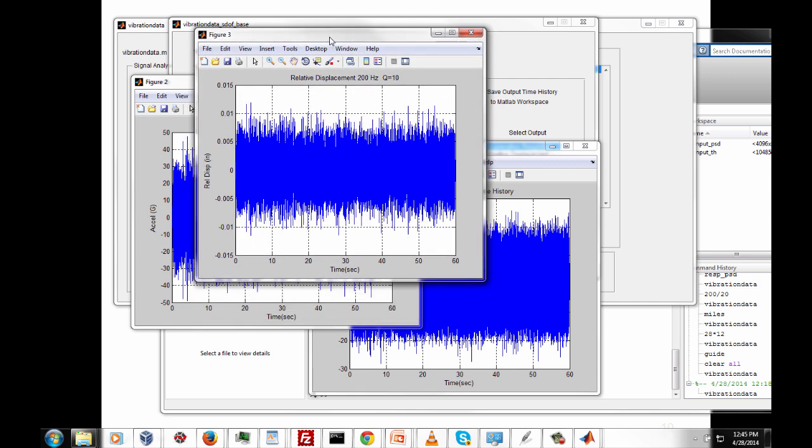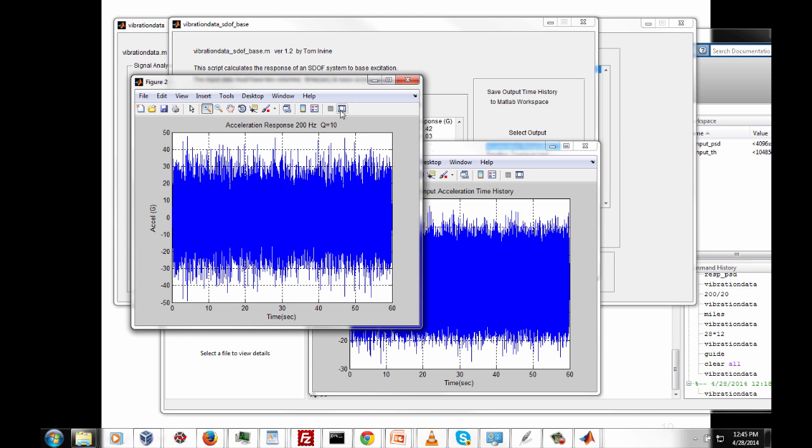We've got a relative displacement response time history, and eventually we're going to be looking at these, especially when we get to circuit board analysis, dynamic analysis of circuit boards per Steinberg criteria. And we'll also, when we do isolation, isolated systems, we have to look at sway space, and relative displacement will be of interest. But we're not going to consider it any further today.